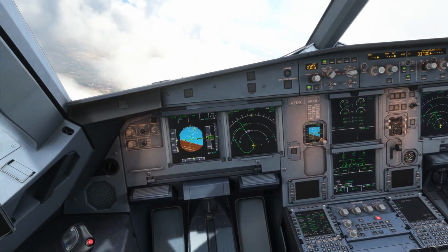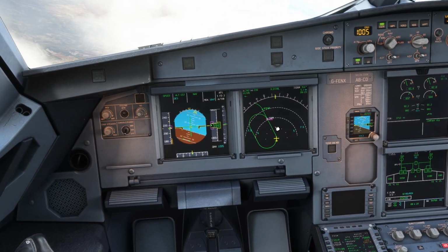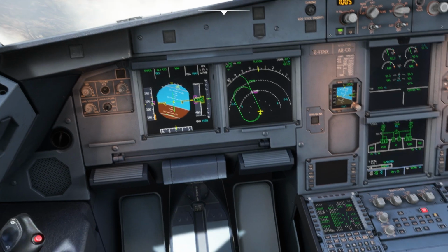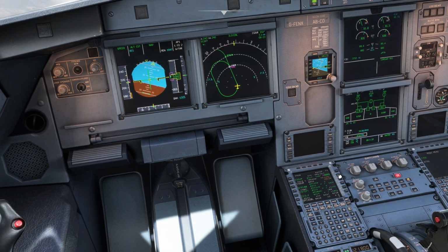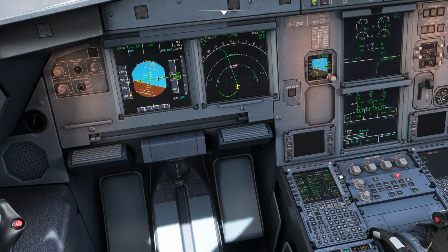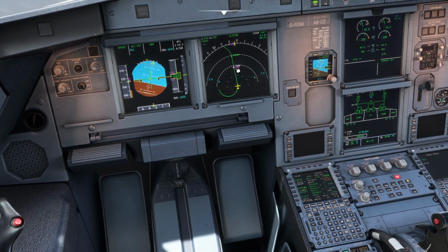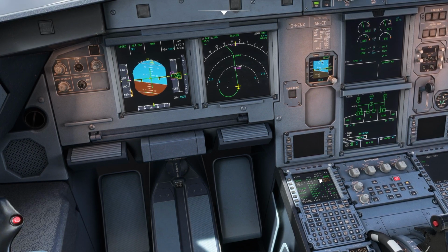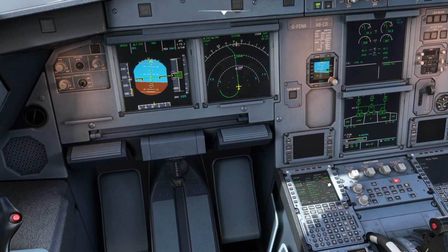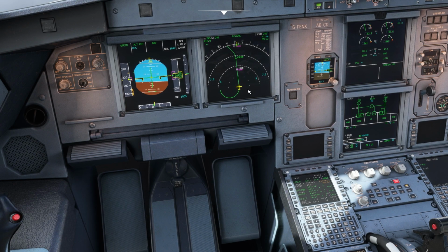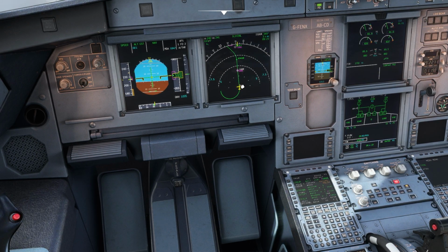Okay, so now as the holding pattern is about to finish, I will press this button, immediate exit. It will ask me resume hold. I will not resume hold. Till the time I have not crossed this option, the resume hold option will keep on coming. If I want to resume the hold again, I can press this button. Otherwise, the plane will automatically get out of the holding pattern, and this option will stop coming over here.